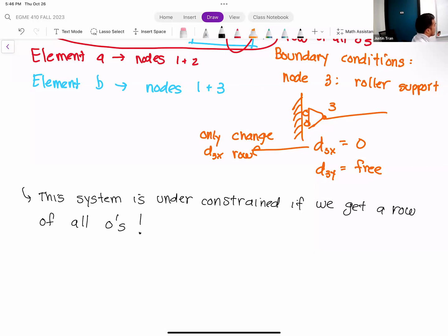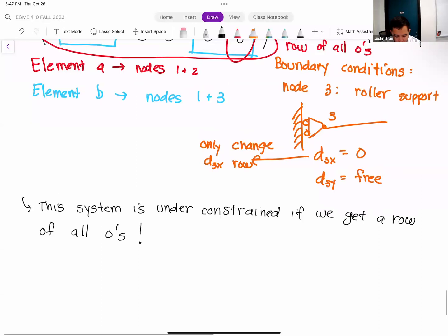Some of you have actually run into this, quite a lot of you at this point. Quite a lot of you have run into this error in ANSYS. This is the dreaded solver pivot warning. If you get the dreaded solver pivot warning, what that's basically saying is that your system is under constrained. That could be due to a lack of fixed supports, or to your connections not being all tight. For whatever reason, your model is under constrained and it's not able to maintain that geometry.